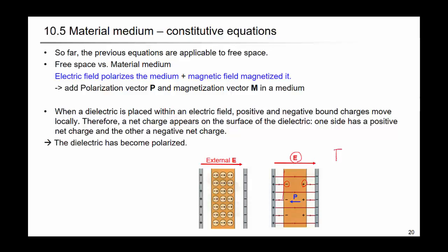So the force resulted by the external electric field will be the same as the force by this polarized one. This is very natural because if the force is not balanced, then this material will move. As long as the material doesn't move, the inside charge doesn't move, which means all the forces are balanced. So this polarization vector is added when you put the dielectric material.